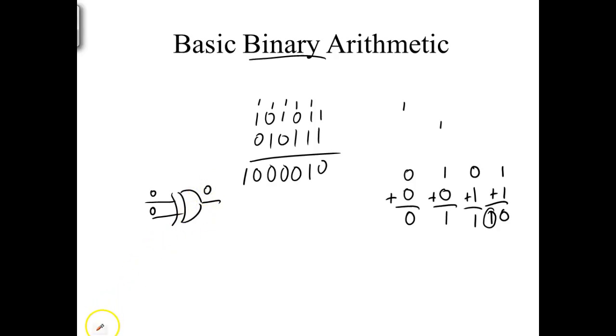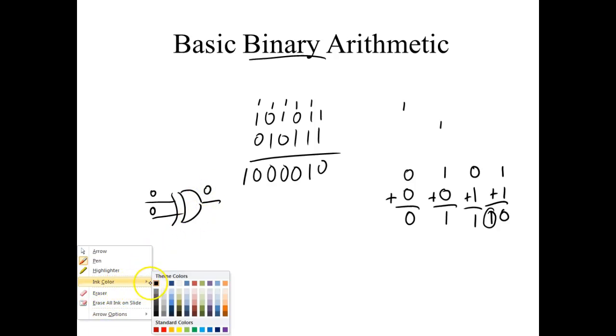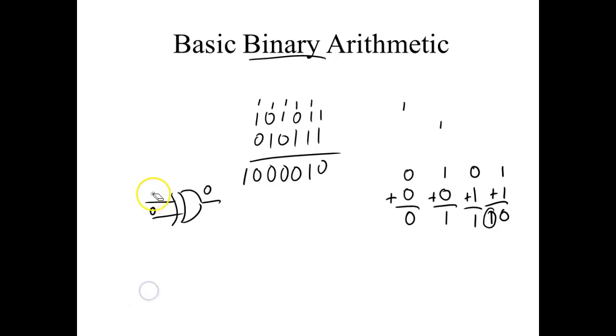0. Let's come over here and let's say, what would I get? They're all the same. This symbol right here tells me what I get when they are not equal. So this symbol right here would tell me I get a 0 if they're not equal. This symbol tells me I get a 1 if they're not equal. So what the output on the symbol does, it tells you what we get when they are not equal.